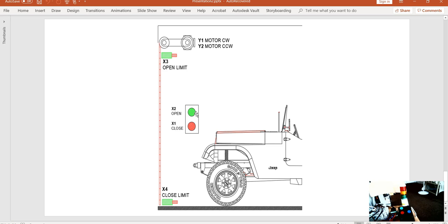And so it'll be a full HMI. And one of the things that we kind of left open at the time was if the door is going open and somebody hits closed, what do we do? And I thought about it, and if it's going open and somebody suddenly hits closed, it should just stop. It should neither go up nor down. If they made a mistake and don't really want to go up, you can hit it once to stop it, and then hit it a second time to close it. So it'll be 2 distinct events.